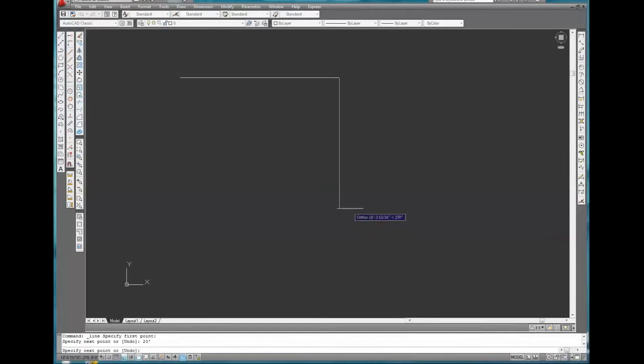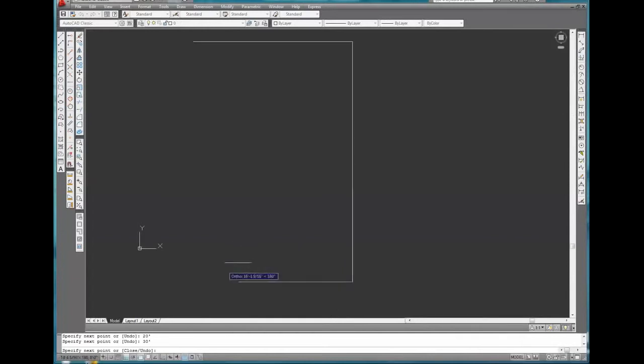Now if I just keep going, I don't have to click the line again. I can just pull down, and now let's go 30 feet, enter. And of course, if it was metric, then you would just use a metric equivalent of that, or a metric unit of some kind. So let's try again here, and let's go 20 feet using the apostrophe symbol again for feet.